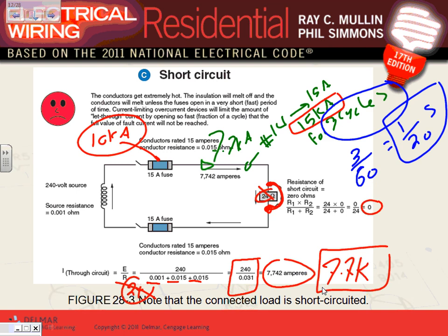Any questions, guys, about the short circuit? I can't emphasize enough the ability to understand it, guys, because that's how we're going to be working as we go to commercial. We're going to size equipment based on the short circuit. Any question about the short circuit condition and why it's dangerous, and why the conductor has to be rated to handle it as well as the fuse?